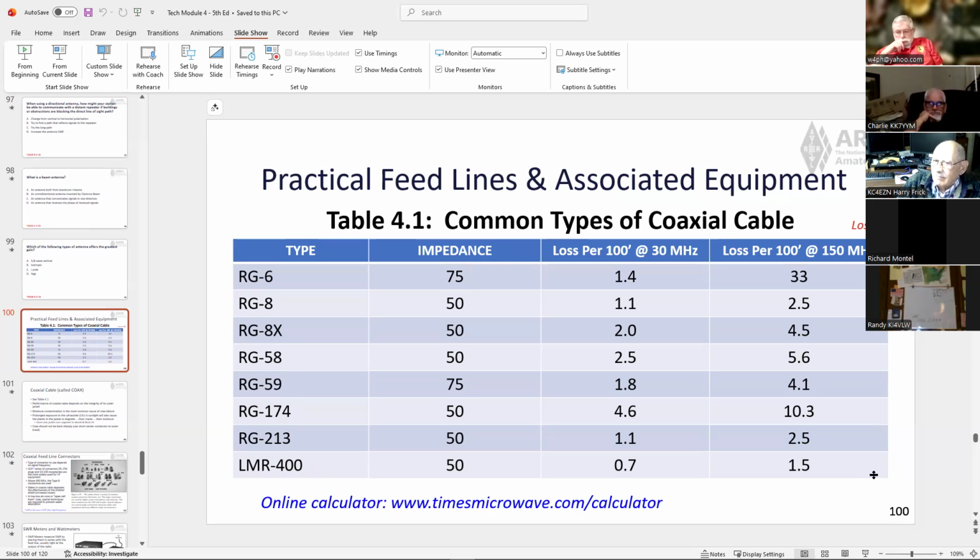How much am I gaining in my antenna? How much am I losing in my coax to get out to that antenna, and so on. It's not hard to do. You just add up the losses in the coax, so many dB, and the gain on your antenna, so many dB, and you can figure out if you're overall ahead or losing.